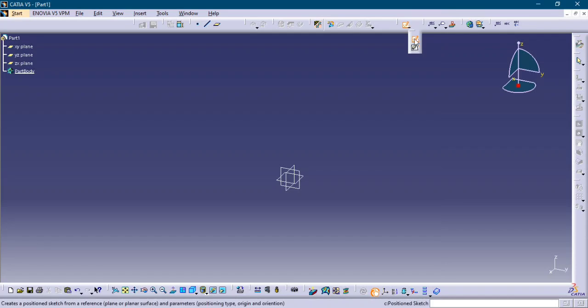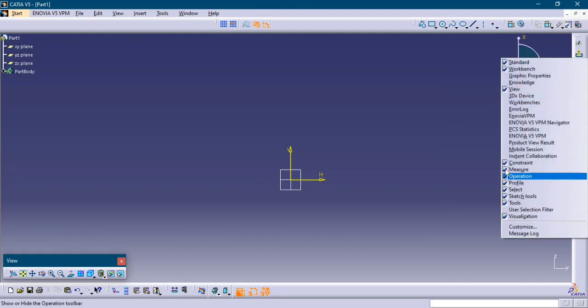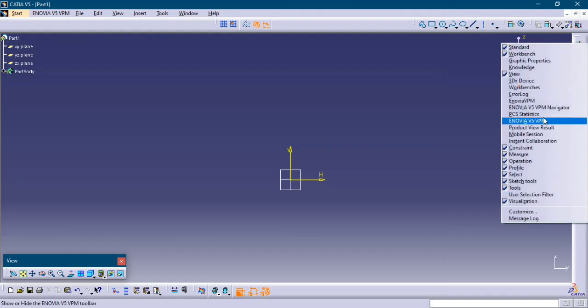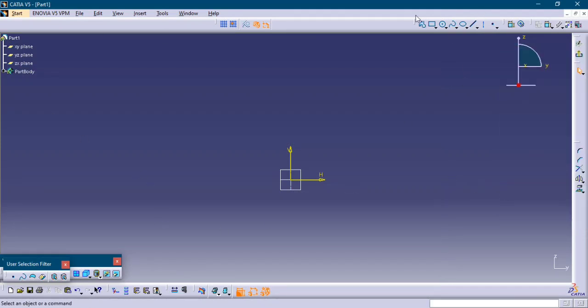First I have to choose which type of sketch I want to do. I am choosing the sketch, and I am choosing the plane. Choosing planes is also important. I have chosen the front plane. After that, here you see it is a sketcher workbench. How can you identify it is a sketcher workbench? On the top toolbar you can see there is a profile toolbar, and the tools required for drawing the sketch exist there. So it is a sketcher workbench now.